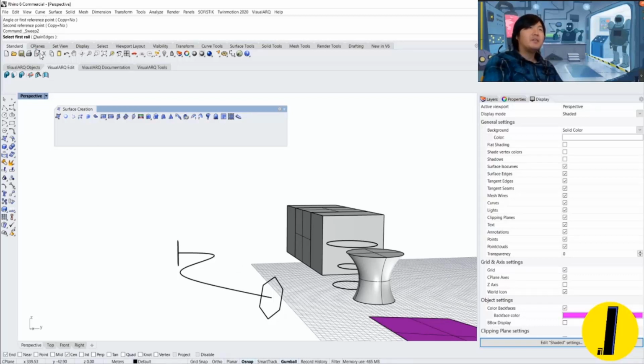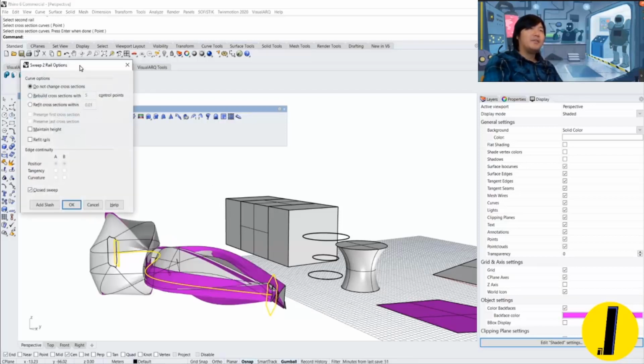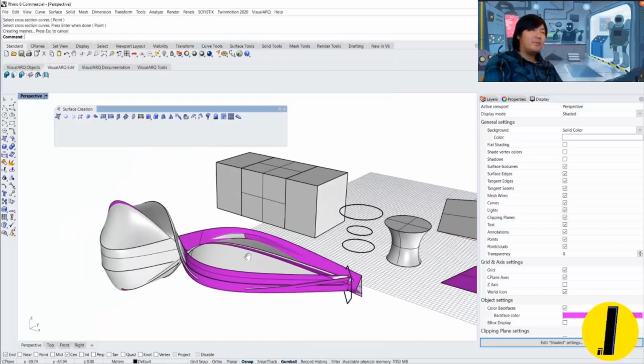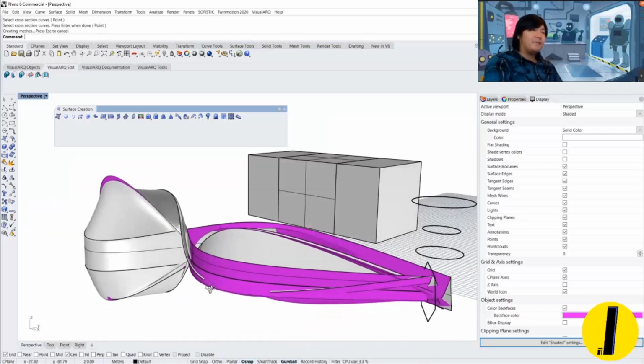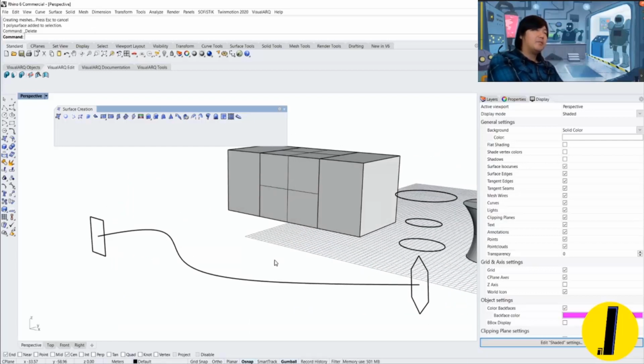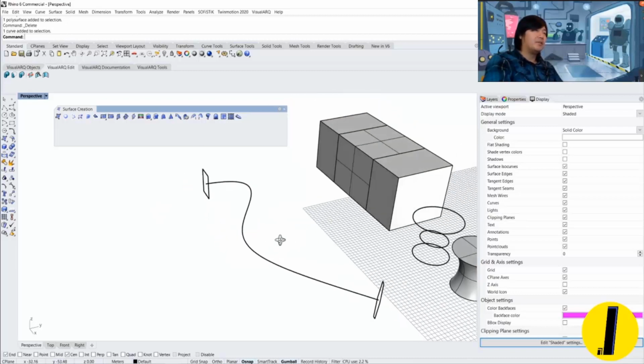It says first layer, select the first layer. In this case, the layer is not that, but I want to use the profile as a layer, and I want to select the second layer, and then these actual curves as a cross section. So when you use it, it's kind of a mess. It's complicated to do this kind of job in Rhino. In this case, it's probably better to use another solution, because that profile and this mathematical path is a bit complicated for Rhino to create.